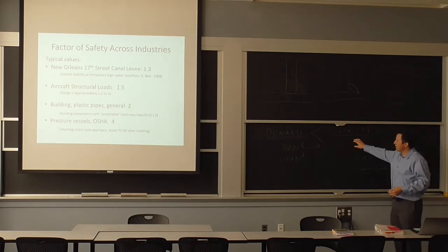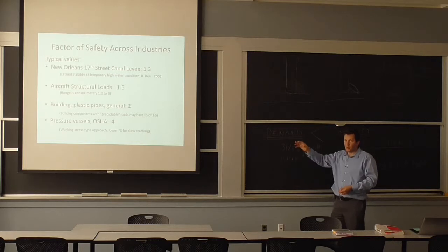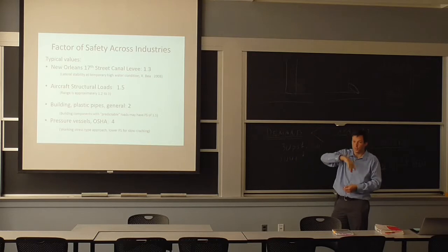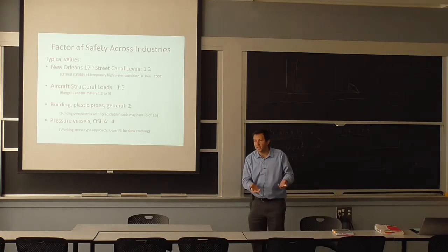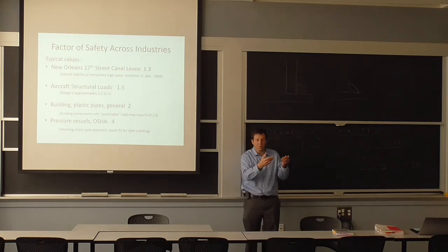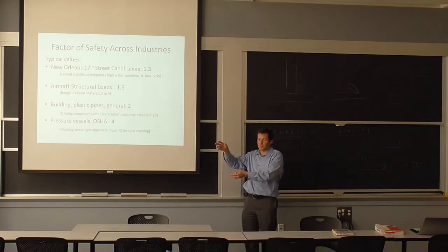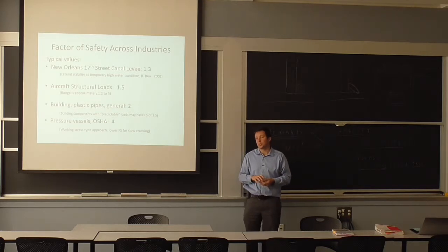So if they start with that, and they know very, very well the sea water, if it goes above the levee, there won't be more load than that. It's just going to go over. So once you have a very specific height for a levee, it gives you the hydrostatic head it's going to be subjected to. When you put these two together, you know the worst soil you can have. You take that, and then you know the height of your levee, you calculate the pressure head from that, and it gives you a number, only a factor of safety of 1.3.